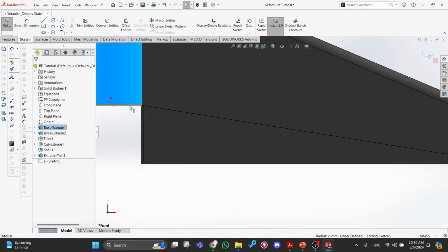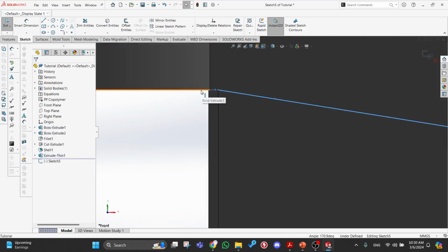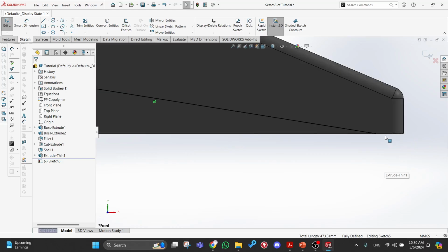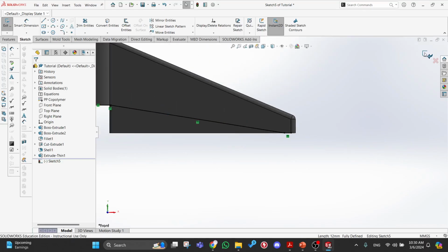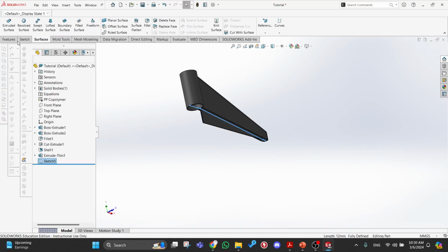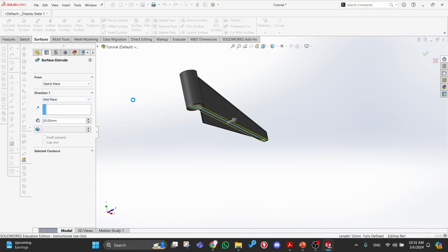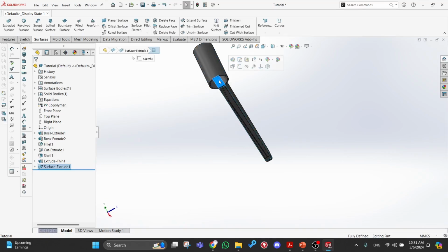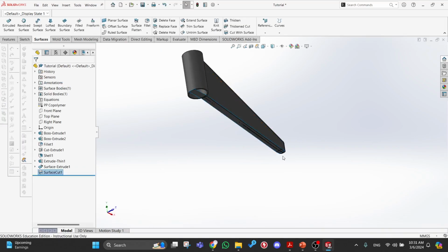I think drawing yourself is faster, but let's just ensure there's no issue. Okay, so here, just convert entities, and then you'll have a surface plane that can be sliced up basically. Click on this, click on cut surface, in your surface, click down, bam.